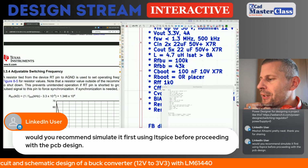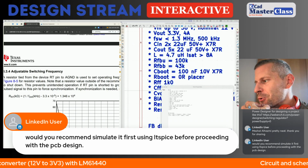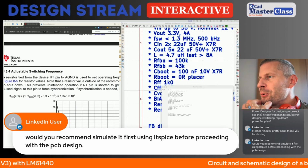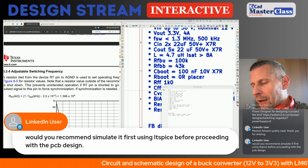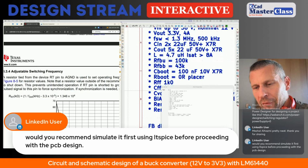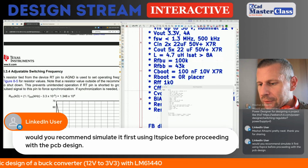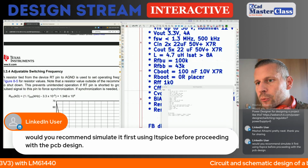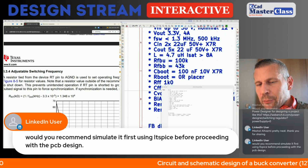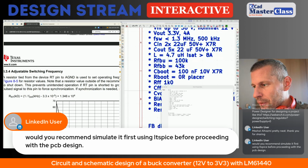Yeah, definitely it's better, but there is an issue. You need models of the components, and not every manufacturer will give you, let's say, open models. Texas Instruments will give you some encrypted SPICE models, but you can't use the encrypted SPICE models in LTspice.